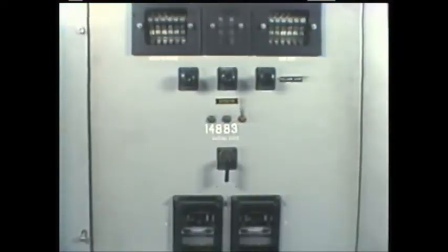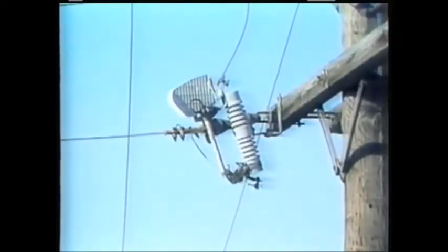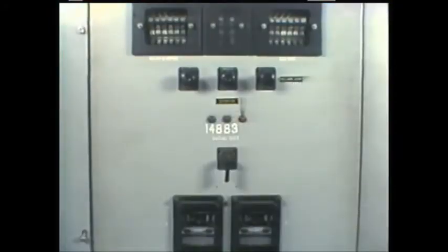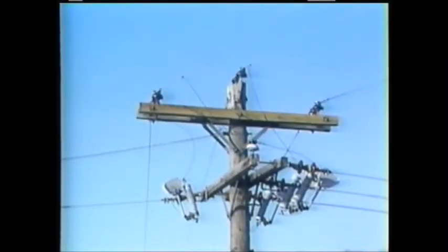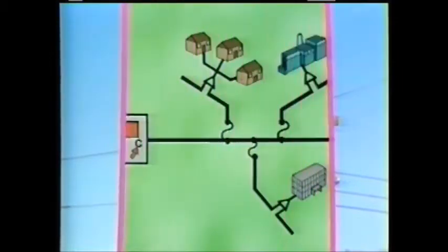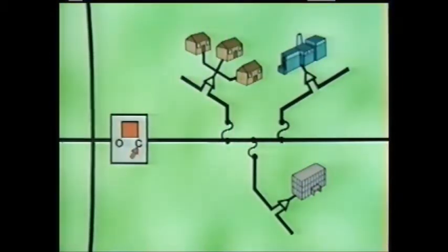Unlike circuit breakers that can open and close automatically, a fuse is designed to open and remain open whenever the value of the current carried by it exceeds its designed capacity. In most distribution systems, circuit breakers and fuses are designed to work in a coordinated manner for system protection. We'll use a simplified drawing of a feeder with fused laterals to see how this coordinated effort is achieved.